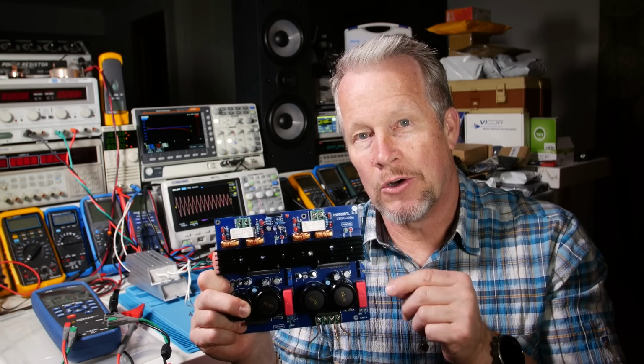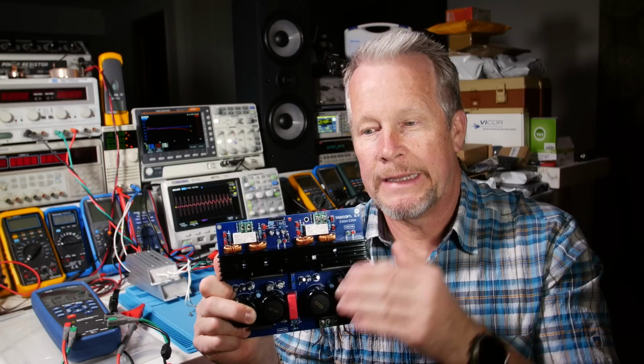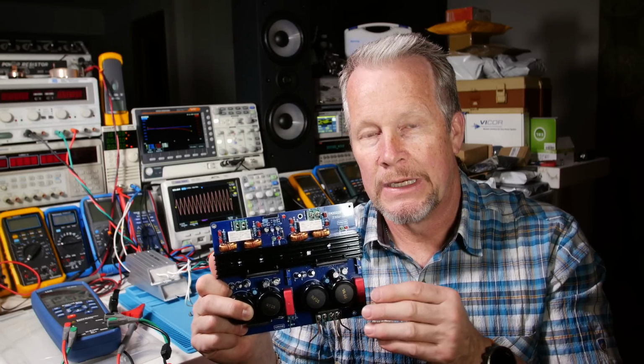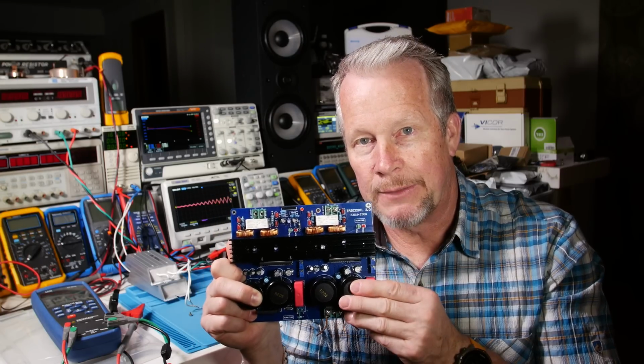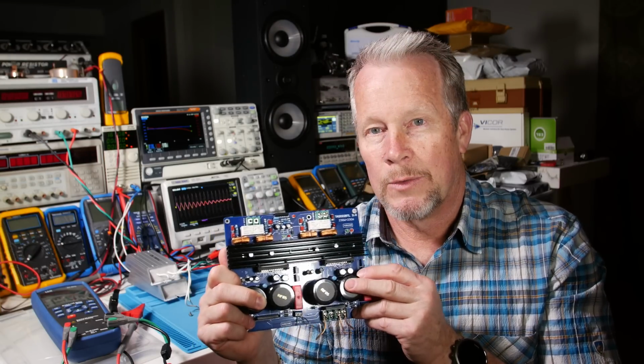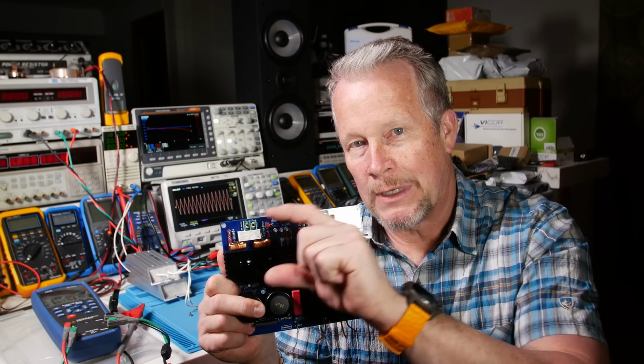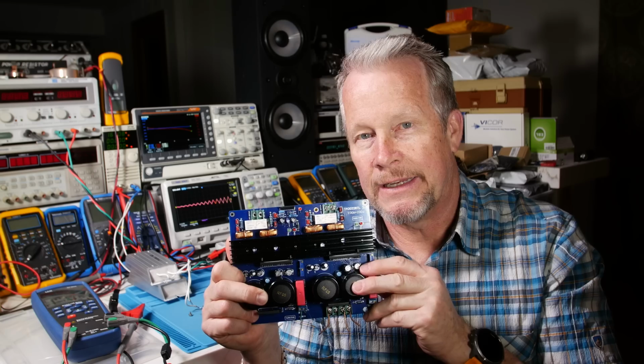We're going to use the scope, which anybody can do with any scope, and we're going to look at the input voltage and the output voltage, and the phase relationship between them. If they're in phase, they'll be right on top of each other. If they're not, they're out of phase. We'll look at that across some frequencies, and we'll be looking at the amplitude across those frequencies to see how steady it is.